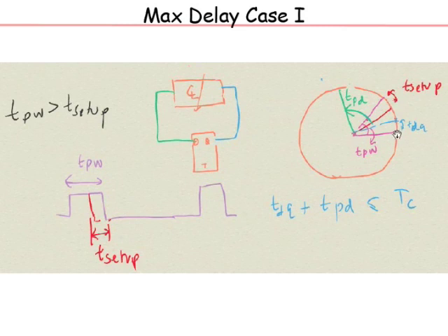I choose one clock edge as my reference, the rising clock edge, and this is 2 pi radians. The rising clock edge keeps happening at exactly the same point every cycle, because this diagram is drawn with reference to the period of the rising clock edge.